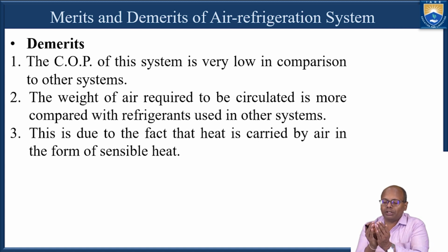So if I use a very small quantity of ammonia also, I can get more refrigeration effect. But for the same refrigeration effect, I need to supply much more volume of air as compared to the ammonia. So what is the reason? That it is the sensible heat.